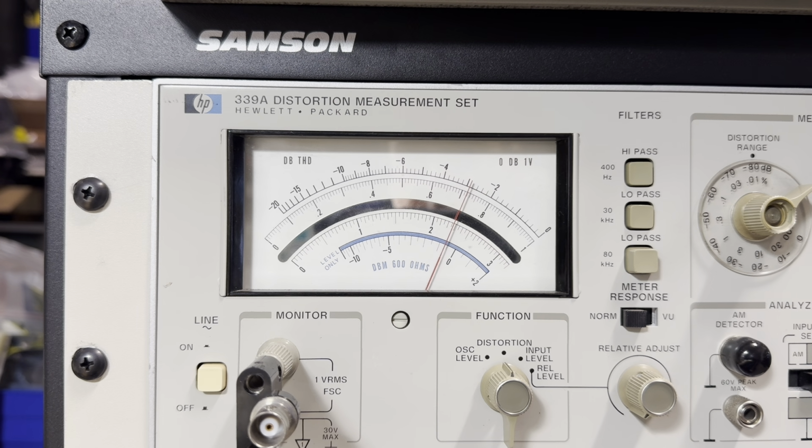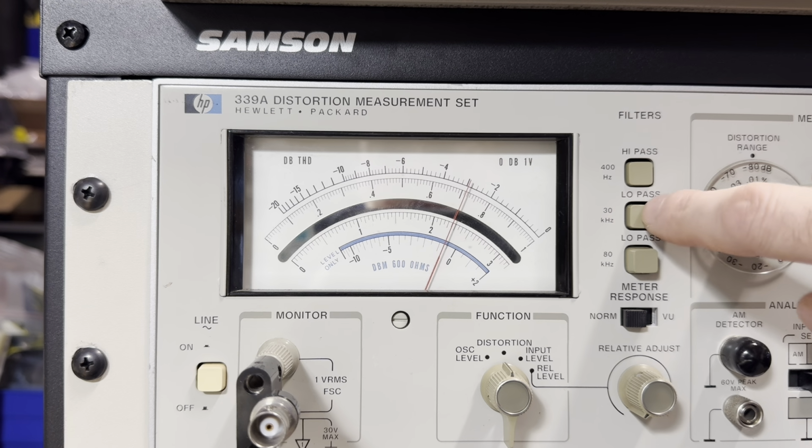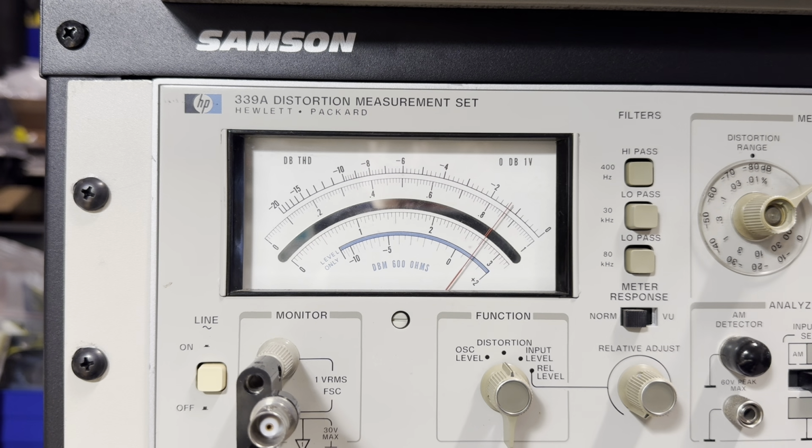almost on our measurement. So you can see how the filters can affect our signal measurement, and based on what we know about our test signal, we can decide whether this filter is appropriate or whether it's not appropriate. In this case, I would say the 30 kilohertz low pass filter for a 1 kilohertz test signal would be appropriate. But if you wanted to be conservative on your measurement, you could certainly apply the 80 kilohertz low pass filter and say, well, that's well within any kind of measurement conservatism there.